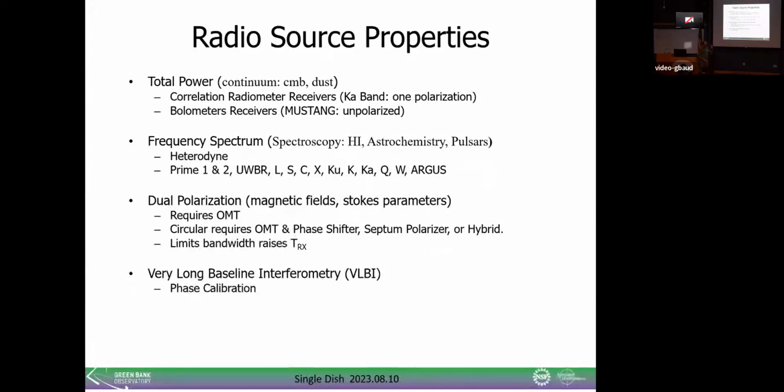It's not heterodyne. It uses transition edge sensors, and it just absorbs photons at 3 millimeters. It's just a photon counter. It's self-contained. All of the total power information from these 223 detectors is just fed back over an Ethernet link. And all the rest of these signal receivers are heterodyne receivers, where you get the spectrum bandwidth transmitted over the optics, and where our back-end processors provide you the